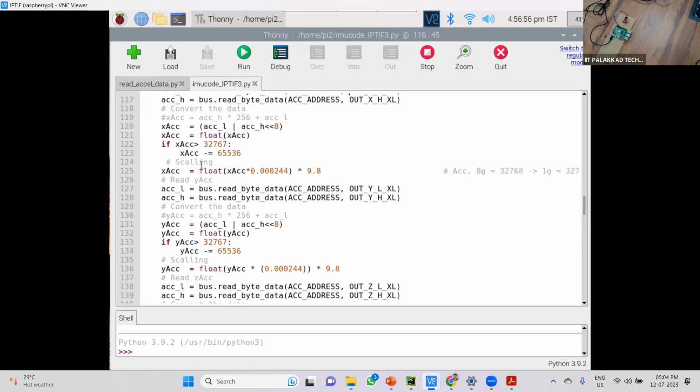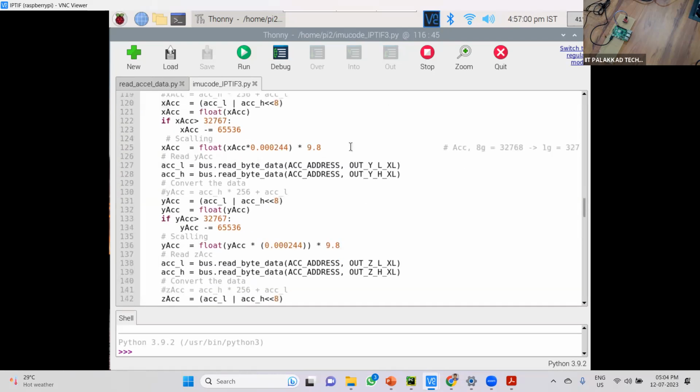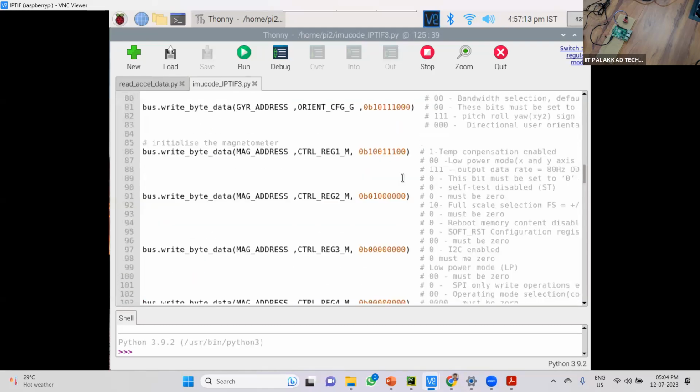And this is my final 16-bit data, right? And there are some full scale value divisions and some gain values we need to divide by for this. Since it is an accelerometer, I'm just taking this. It depends upon how we are writing it initially.